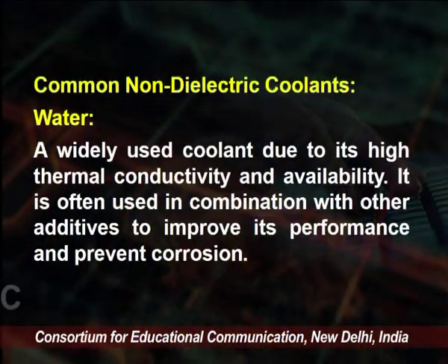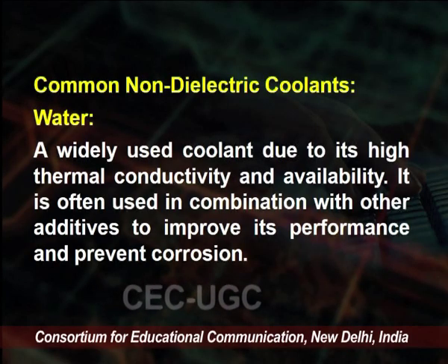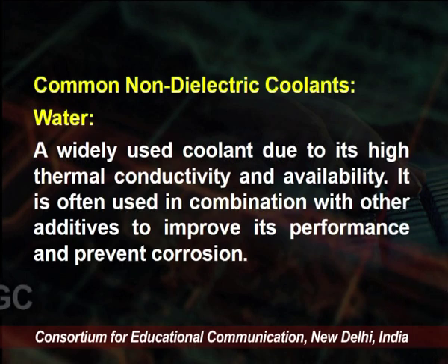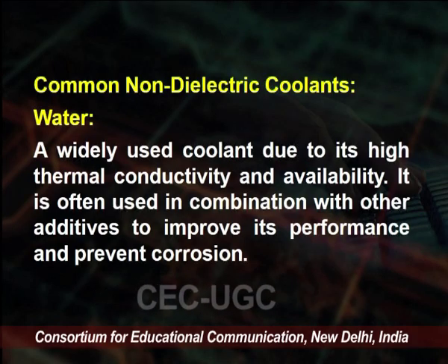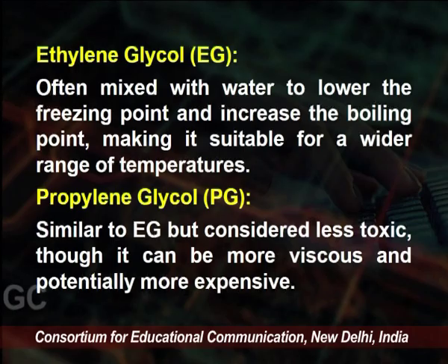Water: we all know very well that water is widely used as a coolant due to its high thermal conductivity and availability, and it is often used in combination with other additives to improve performance and prevent corrosion. Another is ethylene glycol, which is often mixed with water to lower the freezing point.